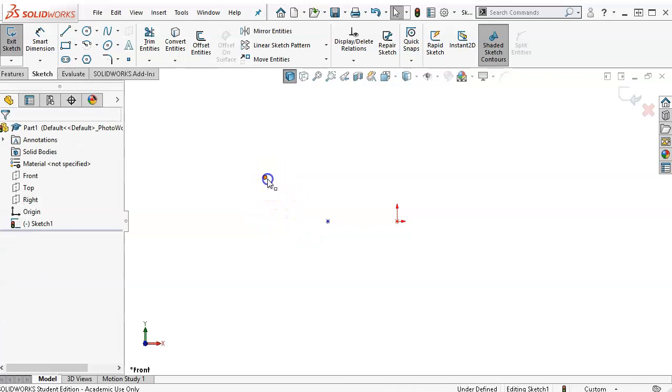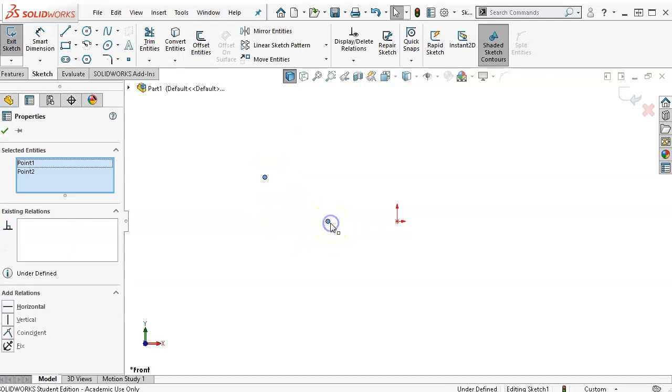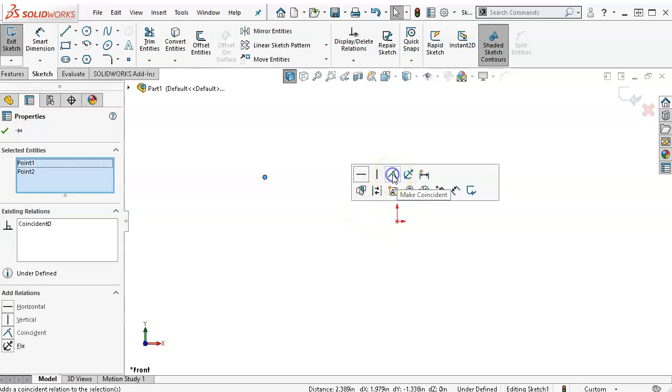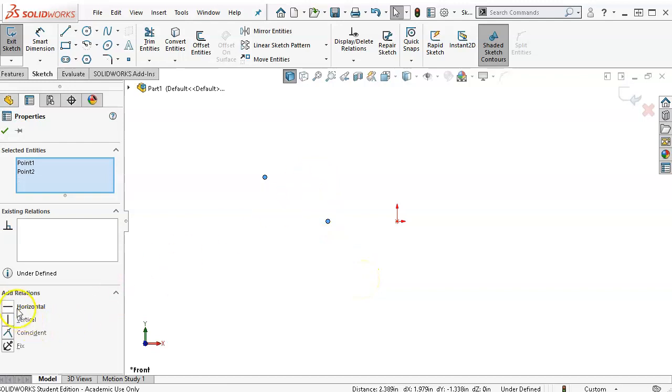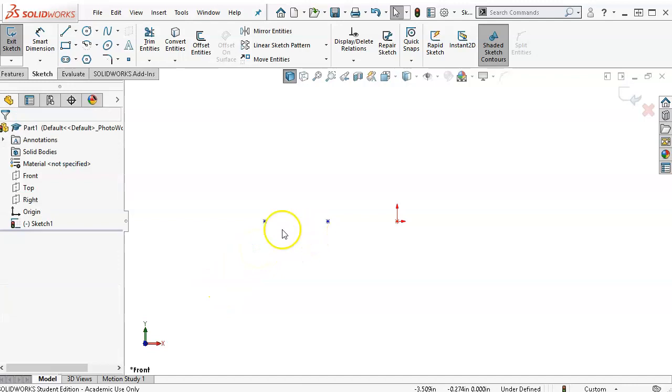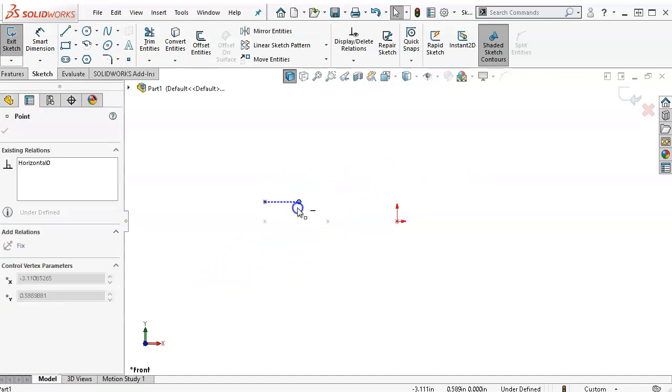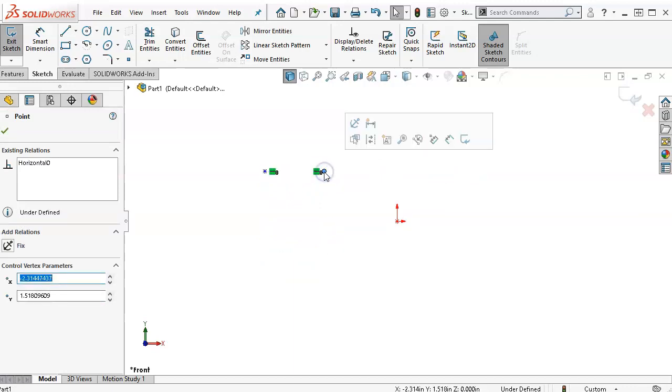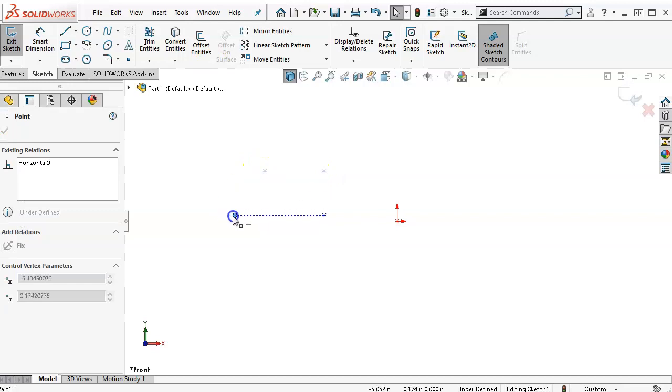That was one of the examples. So if I make the points coincident, and I'm ignoring the origin right now as we go through the steps, the one's going to disappear. We're going to have 2 points occupying the same location. So I'm going to Control Z to undo that. If I go horizontal, then whichever one was selected will go horizontal. And if I also tried to make them vertical, they're back to being coincident. Alright, so Control Z, and as those move, they will stretch and shrink, and we will see the blue for alignment, that those are going to stay in position, and then the distance between the two.